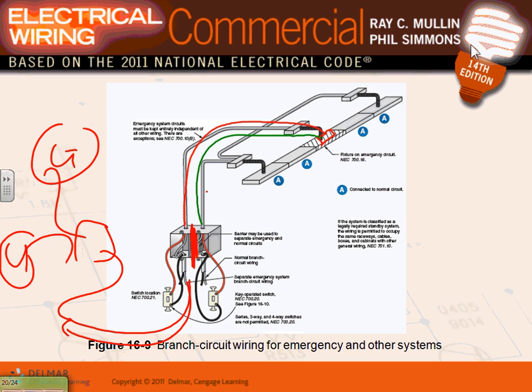If I lose the power right in here, this relay will, like a transfer switch, flip me into the emergency circuit and energize the fixture from the emergency circuit. That's one way. Or you have to key it on. You do it this way, you key it on and lock it. You don't want to be able to turn it off, because if you turn this emergency fixture off, there's no way on earth you can turn it on again. Auto, yes sir. Do lighting fixtures with emergency come with that relay? You have to buy the relay separately. Yep, you have to buy the relay separately.